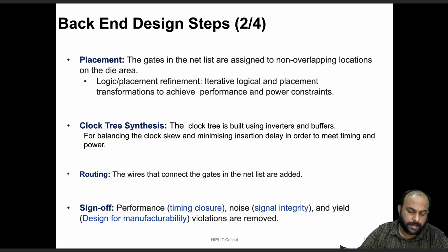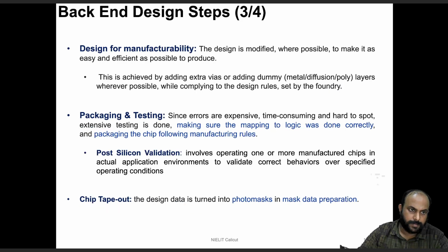So in this step called physical verification and sign off, it checks whether the design meets timing performance, that is, there is no setup time violation, no hold time violations, and so on. Similarly, there are no noise issues, it has sufficient signal integrity, and it can give a proper yield. There are no such violations in respect to timing, signal integrity, or DFM. So these things are taken care of in the physical verification and sign-off step.